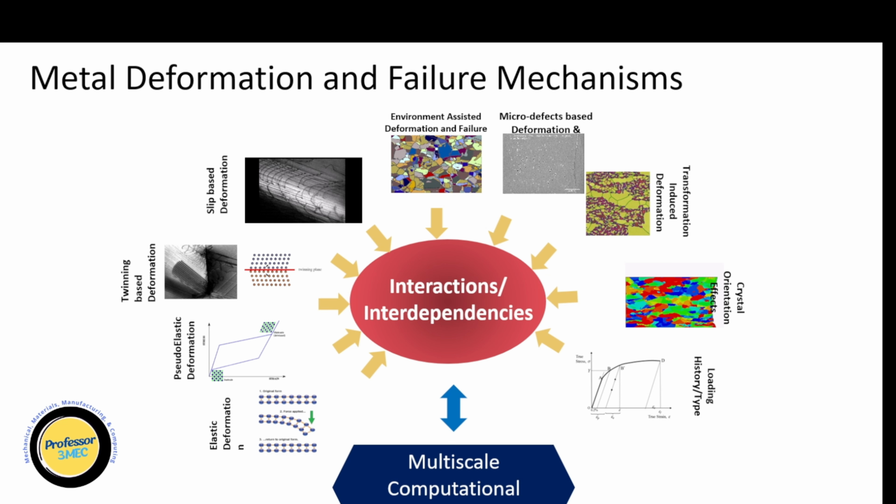So those models are more complicated. I will show you today how to model HCP material using this first, a very primitive UMAT user material subroutine, which accounts for HCP crystal plasticity theory. So let's jump into it.